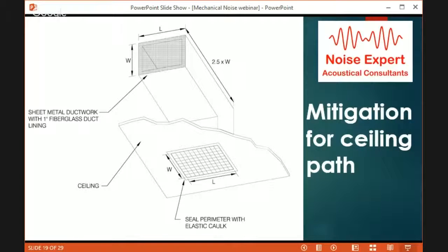It can become costly, especially after the fact, but if a silencer isn't practical or possible, if we're going in after the fact, it might be hard to mess with the ductwork much. And its uses change. Maybe when it was initially designed, the open office space wasn't noise sensitive, and then they've readjusted it or broken it up into individual offices, and they're more sensitive to the noise. That's fine. So what we look at is just an open grill. Like I said, noise travels a lot like water or light. Just an open grill is not doing much as far as attenuation.